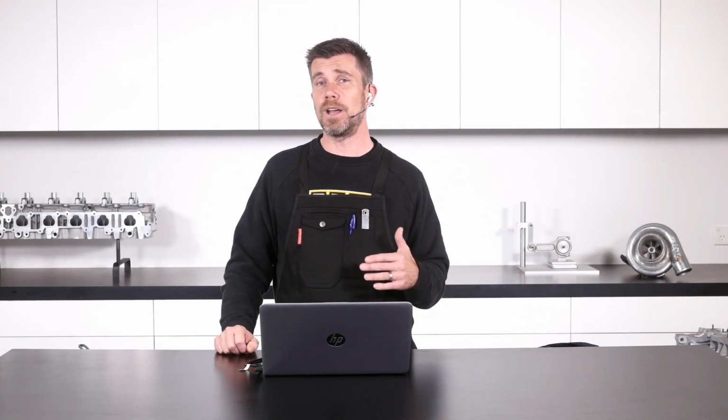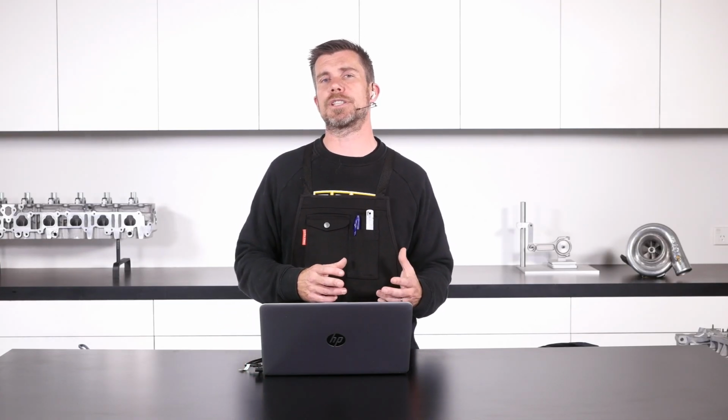So as turbocharger technology has moved on, this has basically moved the goalposts a little bit on what we would previously have considered acceptable for EMAP ratios. However, regardless of the turbocharger you're running, once you've got some data on the exhaust manifold back pressure, you can start to see, as you are increasing the boost on the dyno or at the racetrack, where you get to a point where the turbocharger is becoming a limiting factor. And you can also test with a different area ratio housing for your turbocharger or a different turbine wheel. You can then test and see how that impacts your exhaust back pressure.